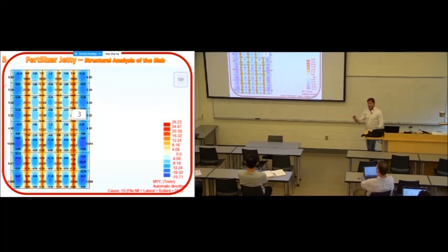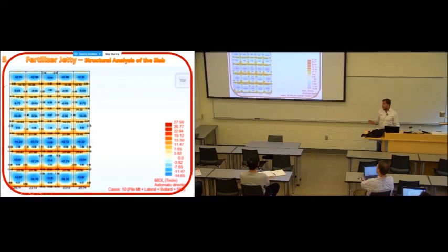Moments in the slab portion: the slab is designed as a waffle slab with beams in both directions that are 120 centimeters high, or 1.2 meter beams, and the slab on top is 50 centimeters, or 0.5 meter. So what you see here is the moment distribution in the slab in the direction parallel to the ocean. And this is the other direction, perpendicular to the ocean.